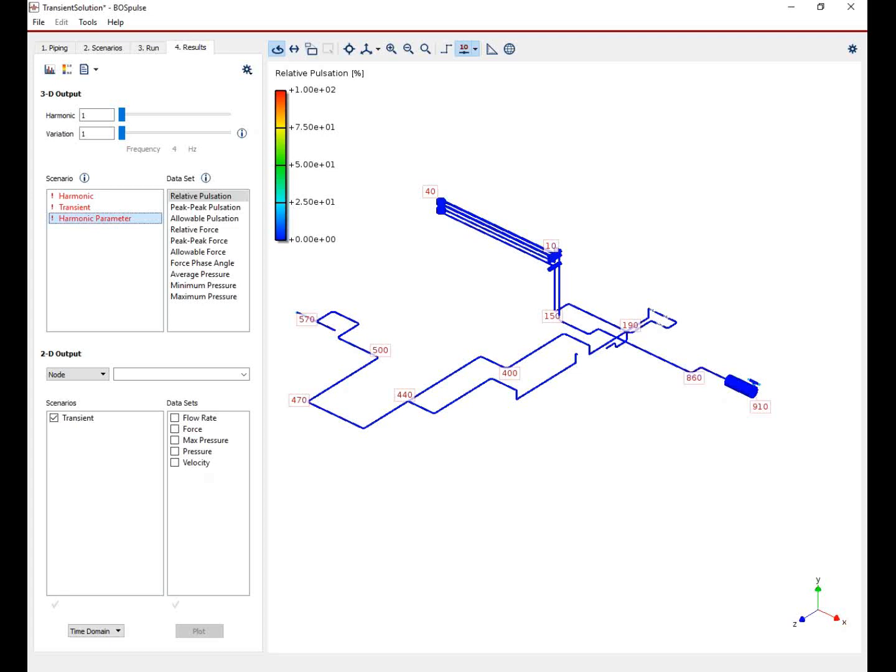And then another approach is to solve it mechanically. So you say, okay, we have those shaking forces, but we're going to restrain the pipe well enough that the shaking forces do not cause any vibrations. That most often means you need to supply some actual stop inside the line that's vibrating, and stiffen up your supporting underneath that support. That's also often an issue, especially with higher piping.